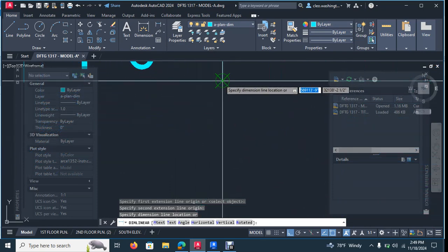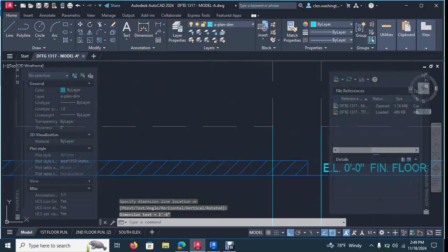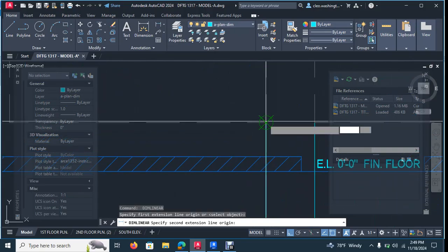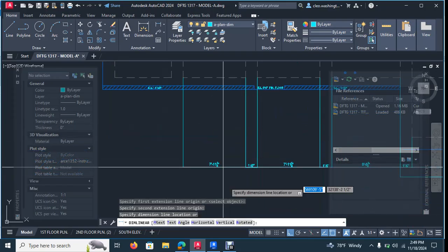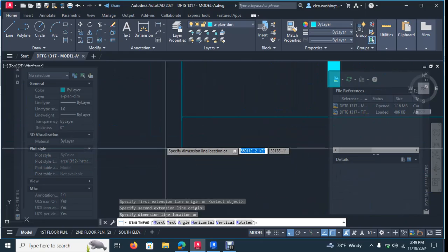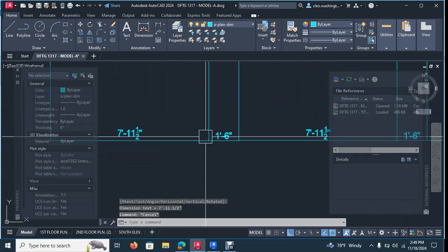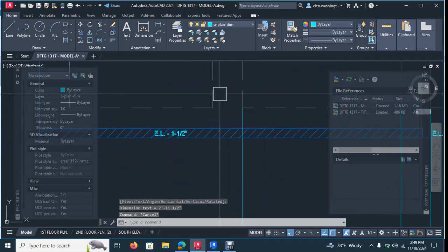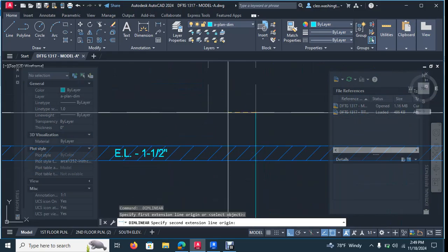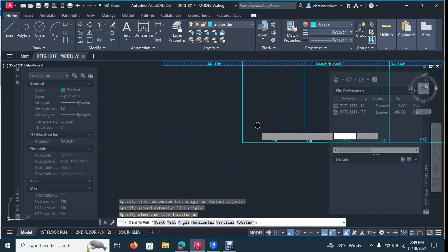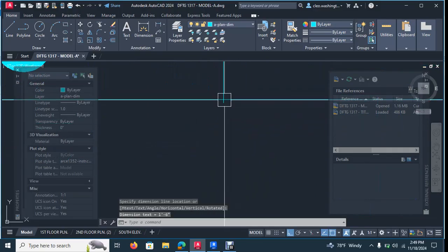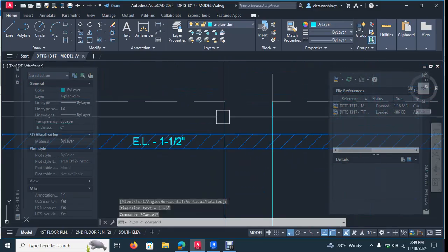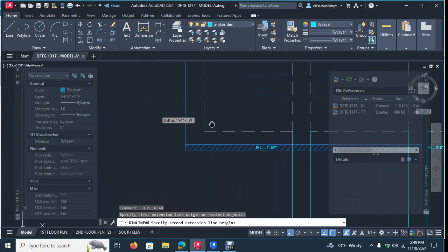They'll mark all of this stuff off. And then what you have is what's known as a pre-pour inspection. You go out to the site and meet with the contractors and inspect the slab, inspect the grade beams. You want to inspect the rebars, making sure that they have the right rebars in there. You want to inspect all of the seats that are housing the welding wire fabric, make sure none of them have the capacity to be moved out of the way or turned over.